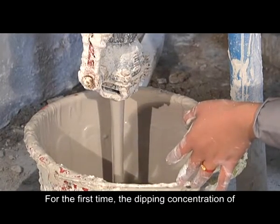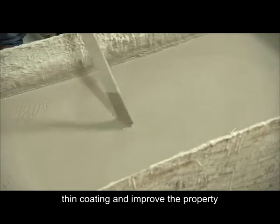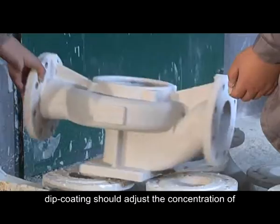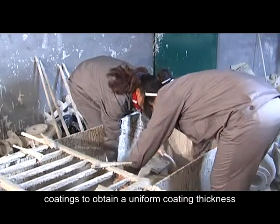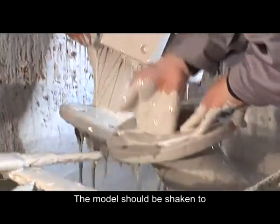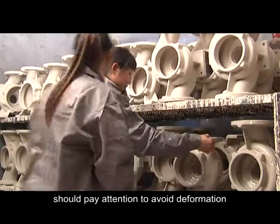For the first time, the dipping concentration of coating is relatively small to obtain a uniform thin coating and improve the property of the second coating. For the second or third time, dipping should adjust the concentration of coatings to obtain a uniform coating thickness. The coating layer should be uniform and may not have any reservation. The model should be shaken to remove excess coating. The delivery and placement of the patterns should pay attention to avoid deformation.